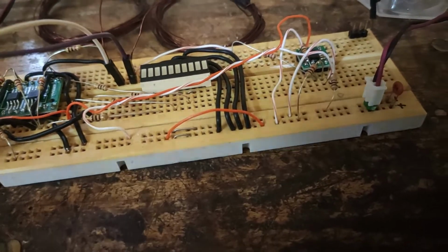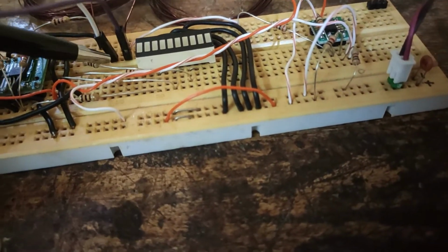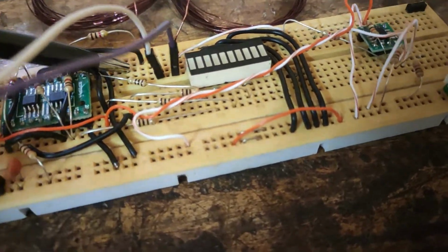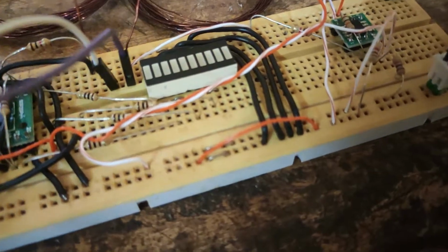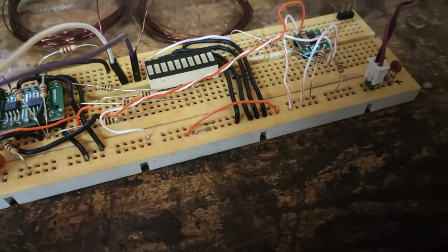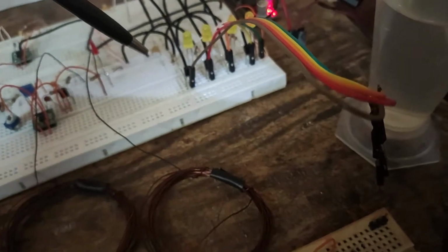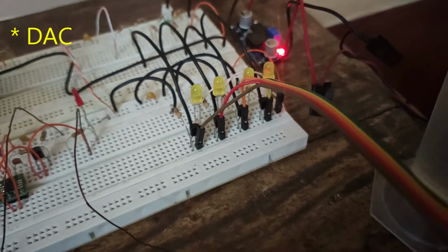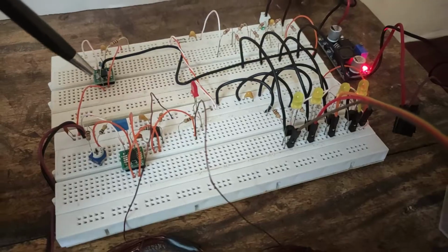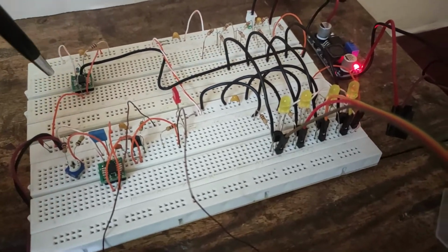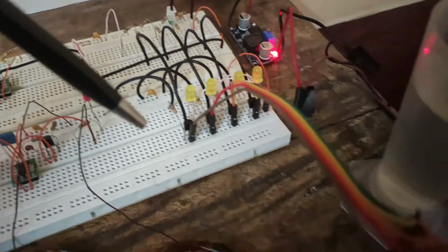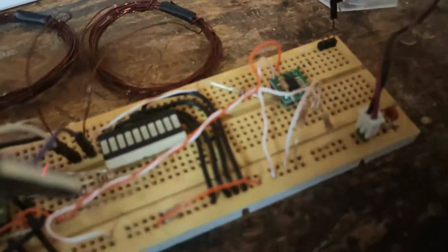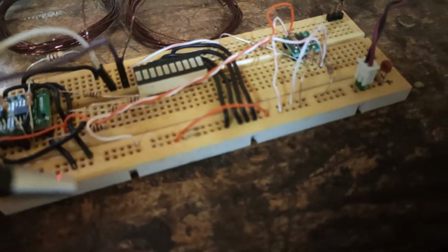This is the receiver side of the 4 to 20 milliampere current loop. Here comes the one end of the loop, and by putting a voltage drop resistor and measuring voltage across it, we would be able to interpret the state of these LEDs, in the sense the output of this R2R ladder. So overall, what all these sections do is simply encode this digital value of the water level into the current, and based on small variation in the current, you would be able to pick up that differential voltage, and again